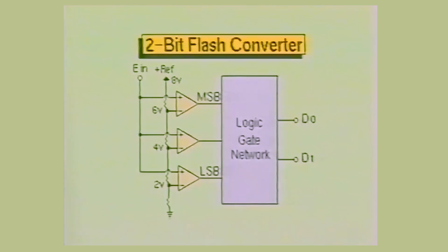Very few analog-to-digital converter circuits are as fast as the parallel converter. The conversion speed of this converter is so fast, it is often called a flash converter. The flash converter uses a bank of parallel comparators to process the analog input signal. One input from each comparator in the stack is connected directly to the analog input signal. The other comparator inputs are biased by a DC reference source through a simple precision resistor network. The resistor values are chosen so that each comparator is biased one least significant bit higher than the next one down in the chain.